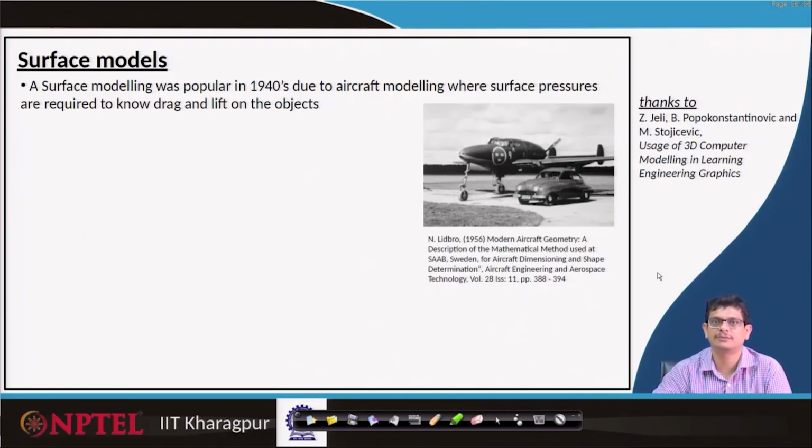What should be the surface? Because the olden days aircraft always had an internal structure, and you would cover it with surfaces. Now, how that surface is supposed to be turned on that aeroplane such that one has less drag and more lift, because earlier constructions did not use typical composite materials. So, they had to deform the object in a nice way, and that is supposed to be supported by the internal skeleton structure. So, deforming, riveting, this kind of process requires surface information, and the entire surface modeling concept actually came in those days, the 1940s.